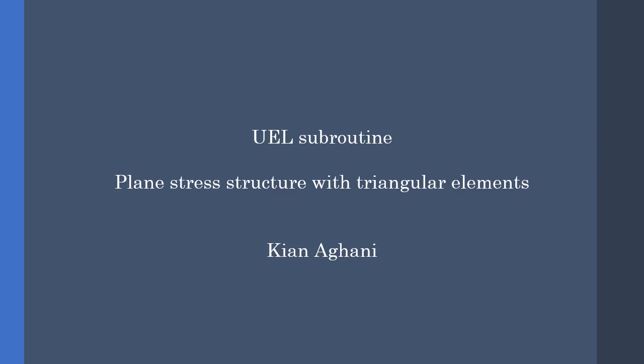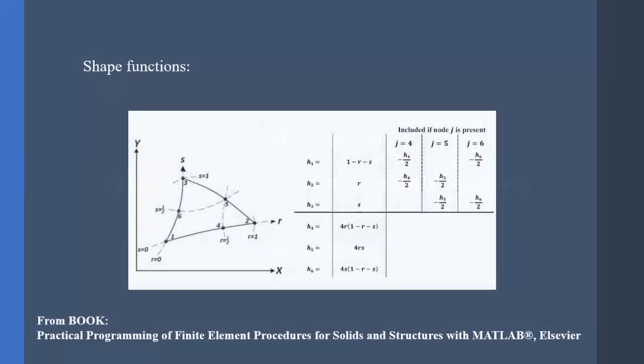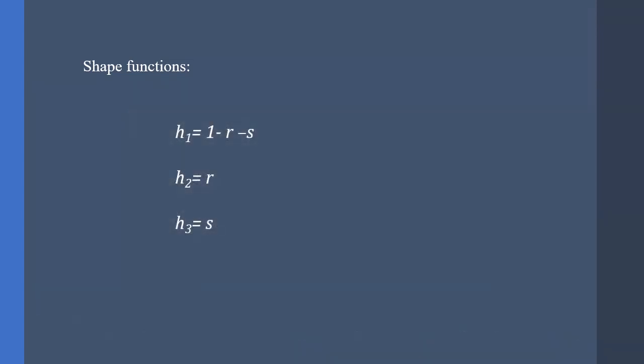Hello YouTube and welcome. In this video, we are going to write a UEL code for a plane stress structure subjected to concentrated and distributed loads using triangular elements. So we note that the shape functions of a triangular element are according to this image. Assuming a 3-node element with 3 integration points, the shape functions and their derivatives are like this.